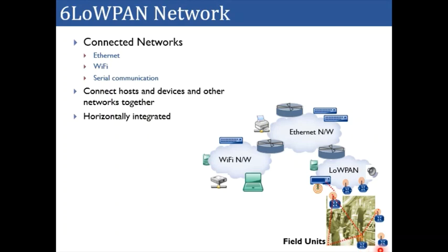In the field, we have various sensor routers utilizing serial communication with the sensor devices, and then the data is pushed to the 6LoWPAN network using the 6LoWPAN router as well as the 6LoWPAN sensor routers, and then using edge routers or 6LoWPAN routers the data is pushed to Ethernet, and since the Ethernet and Wi-Fi networks are interconnected, the data can ultimately be shared with Ethernet as well as the Wi-Fi network.